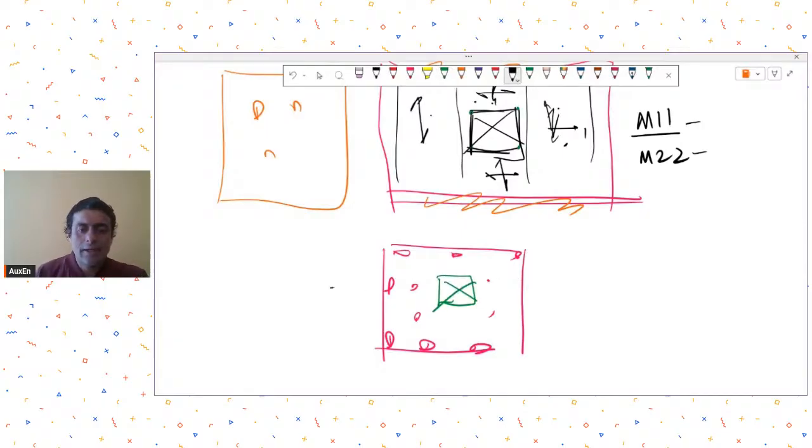The lateral loads like seismic and wind are usually transferred from slabs to vertical elements. So around the openings again there will be a problem because the load path breaks, isn't it? Load path breaks.